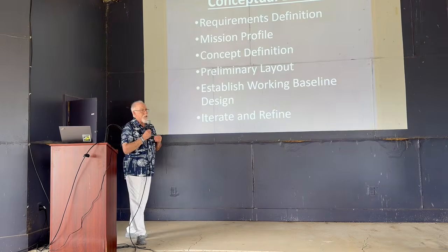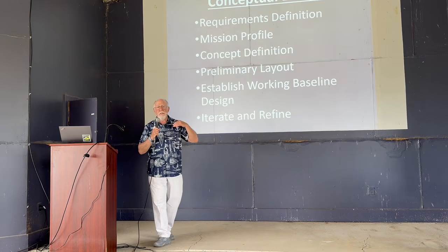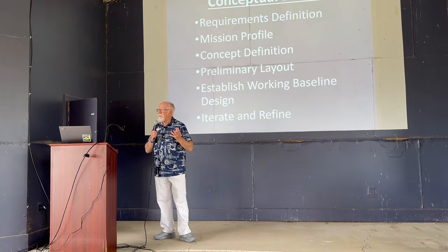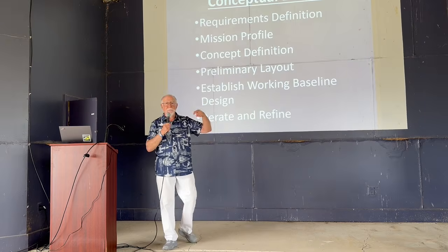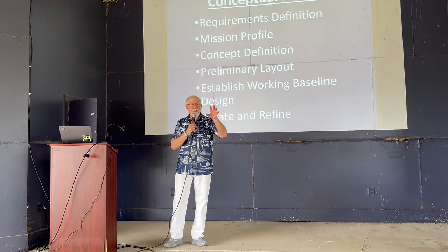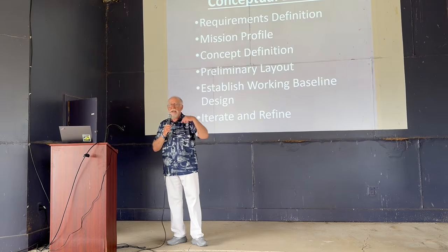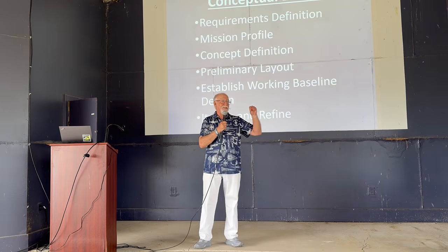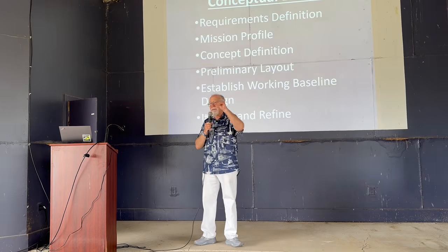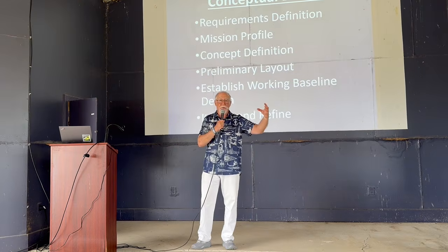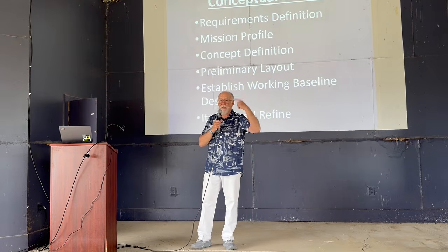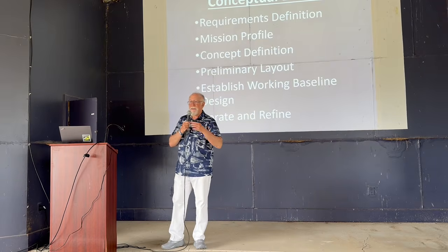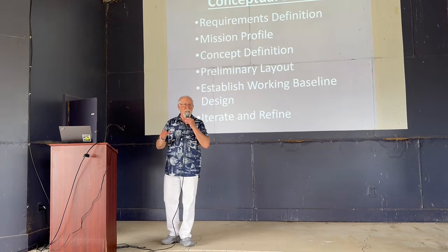So, what we're talking about here is conceptual design, which starts with requirements definition, then we define a mission profile and concepts, then we lay out an airplane, and then we iterate and refine that baseline design. And the importance of a baseline design is really, really critical in that design process. The baseline is the best you have at the moment. Ideally, it is the solution you have now that will at least meet the minimum requirements. And then the objective of each iteration is to knock that baseline off the pedestal with something better until you achieve whatever your criterion for good enough is, and ship it.